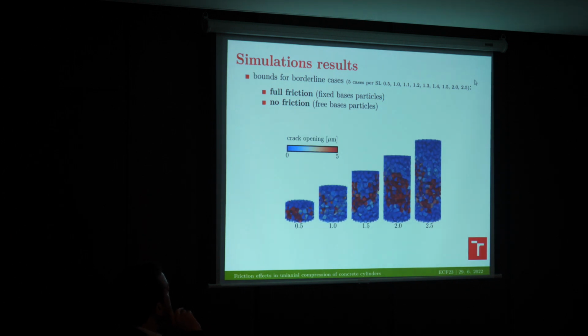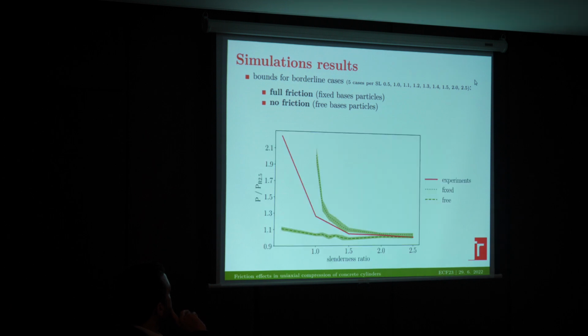Here you can see just a graphic representation from the model, which shows the crack opening which was obtained by the model. Now let's see the results. In red there are the experimental results which I already showed before, and then there are curves for both cases, the full friction and the no friction case. You can see that the free boundary condition